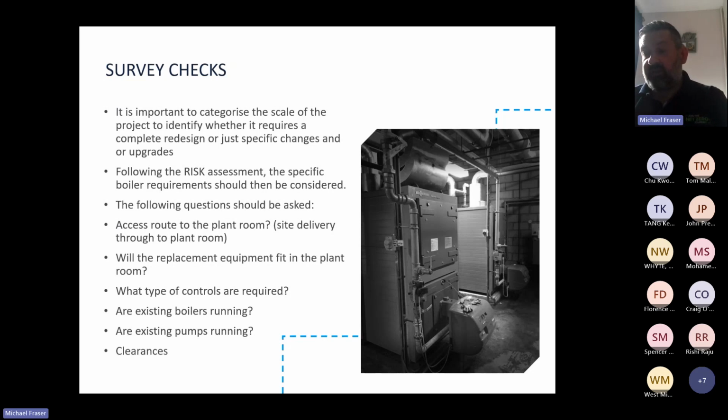So is there adequate space externally to site the heat pump or pumps? Heat pump manufacturers' data sheets need assessing for spacing out requirements, whether installing one or a bank of heat pumps. Is there ground for them to be sited on in good condition? Is external noise going to be an issue? Will attenuation be required?